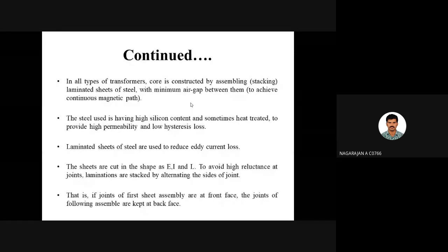Okay, so if you don't understand, I'll just give a point of it. When you increase the magnetic field intensity, flux should be increased. So that is the primal expectation. But in a magnetic core, it will not happen as we require or as we expect. It will increase initially, but when you reduce the supply voltage, it will not come to zero all of a sudden. The flux will not be zero all of a sudden.